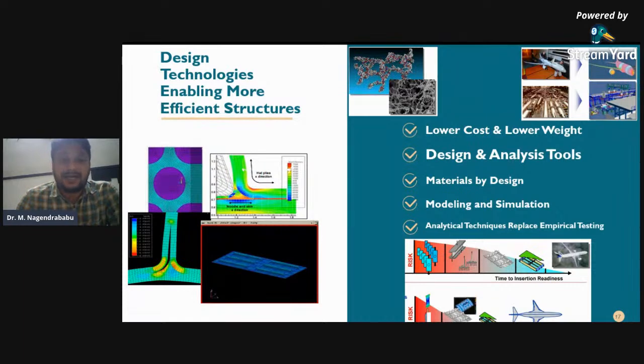Titanium 5553 is another metal that is reasonably new to aerospace, exhibiting high strength, light weight, and good corrosion resistance. Major structural components that need to be stronger and lighter than previously used stainless steel alloys are perfect application points for this titanium alloy in comparison. And titanium 5553 has been a notoriously difficult material to machine until recently.